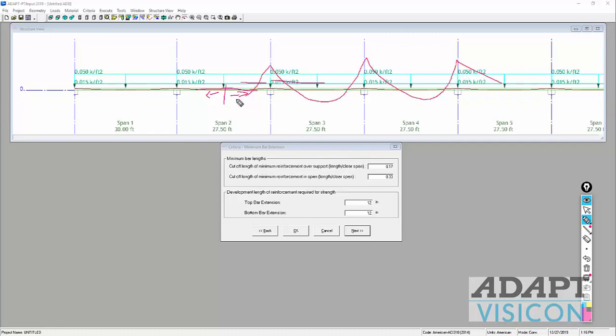So if I have a moment diagram that looks like this, then we determine, okay, where's our cutoff inflection points? There's a 0 moment here and here. The program might say, okay, take half of the demand. If this AS, I'll call it ASM, AS max. If I go down and cut that in half, maybe this location here, this is called, let's say, AS2. The program might require bars to run from 0 to 0 plus the extension that meet AS2 plus another 2 bars that extend past that AS2 mark. And the program's algorithm usually will cut bars into 2 different segments like that to try to economize the design rather than just running the requirement for AS max beyond point of 0 moment. That's what this cutoff is here.